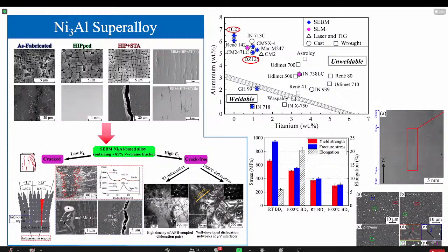There is a term in nickel-based superalloys, people call this cooling-induced precipitate, because high gamma prime fraction nickel-based superalloys tend to contain a high content of aluminum as well as titanium. So in that case, they have a very high susceptibility to get the gamma prime out. So even if you do the normal quenching, you can still get this gamma prime out.